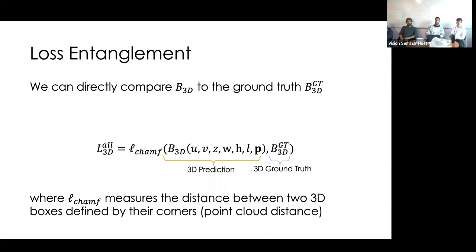Yes. Quick question. In terms of rotation of boxes, you only rotate through one axis? Yeah, exactly. No, we rotate. P is a 3x3 rotation matrix. Okay, cool, awesome. But it's being parameterized, and we actually use the 6D way of encoding it, which is from Howley's group. Basically, how do you encode a rotation matrix? You can do Euler angles. You can do various things. We use the 6D parameterization.